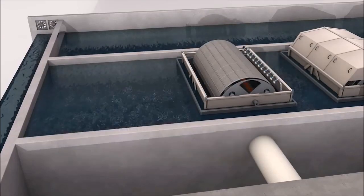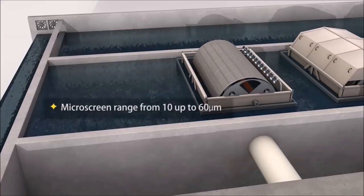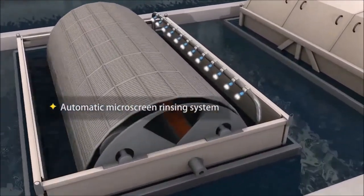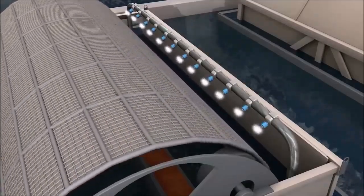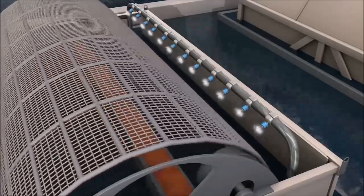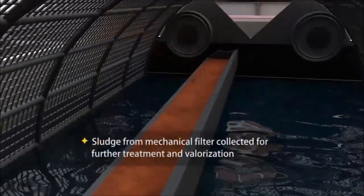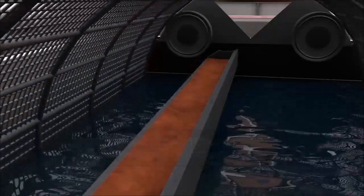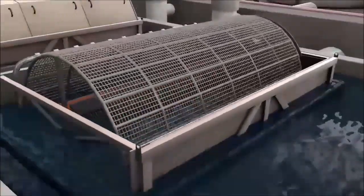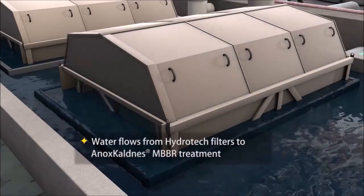The mechanical filtration unit has a drum filter, which you can see moving, covered by a micro screen ranging from 10 to 20 micron size. When it is moving, it is flushed with water, and you can see the flushing by the spraying of the water. Inside the drum filter you can see a path for removing the sludge. Whatever the organic load in the water, that will be deposited in the inner tray and can be taken out as a slurry.